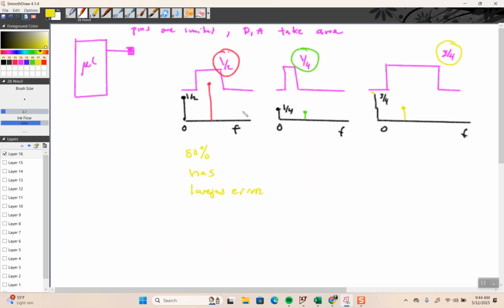So the thing is all these levels will have ripples because I can't perfectly get rid of that, right? An ideal filter would be a box. I give the DC and this goes to 0. Get the DC, that goes to 0. DC, that goes to 0. But that doesn't exist. There's always some signal there, and there's an infinite number of frequencies, so you will see some kind of ripple, and you're trying to get rid of that with a filter, right?